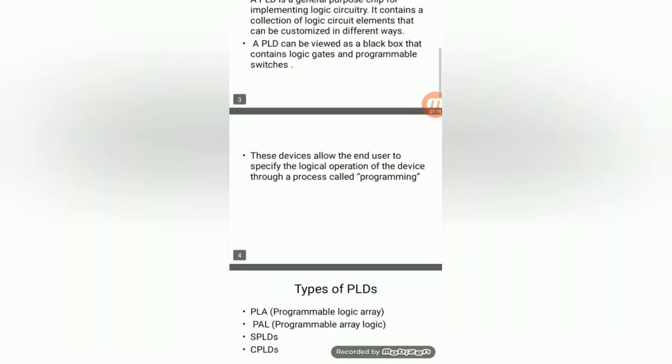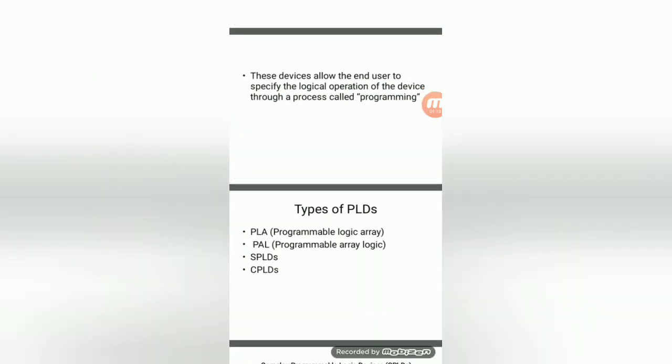There are three types of PLDs available: programmable logic array, programmable array logic, and a collection of PLDs, which is called the CPLD. SPLD means simple programmable logic device, and CPLD means complex programmable logic device. By using PAL and PLA, we can implement simple designs like gates, sum block, carry block, adders. For more complicated designs we can go for CPLD.